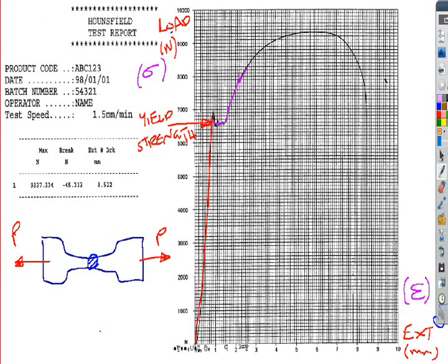As I mentioned last week when we were talking about factors of safety, going plastic can be a failure. It's not necessarily broken, well, it isn't broken. The component is still in one piece and it's actually quite strong, but it can be considered a failure. Going plastic is a failure. So when we talked about a factor of safety last week, the maximum allowable stress could be the yield strength.